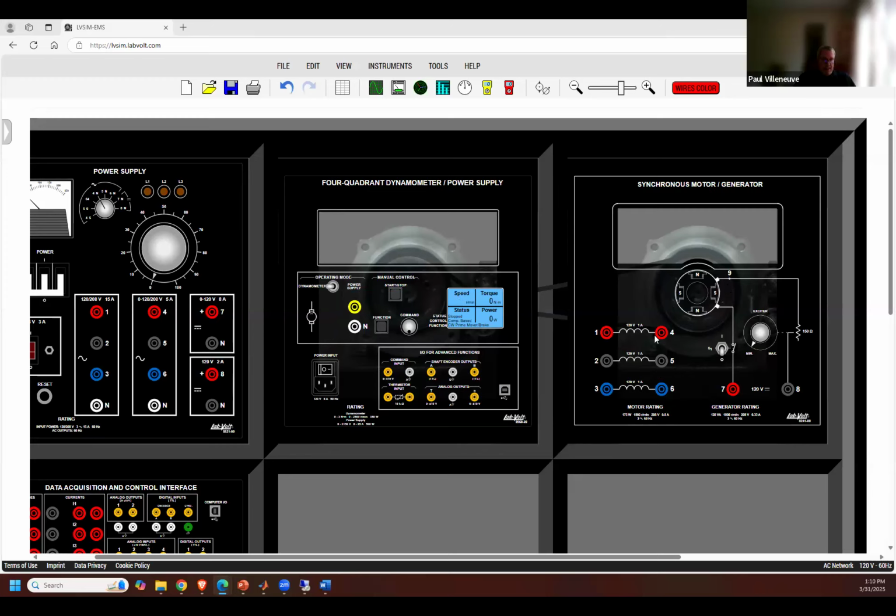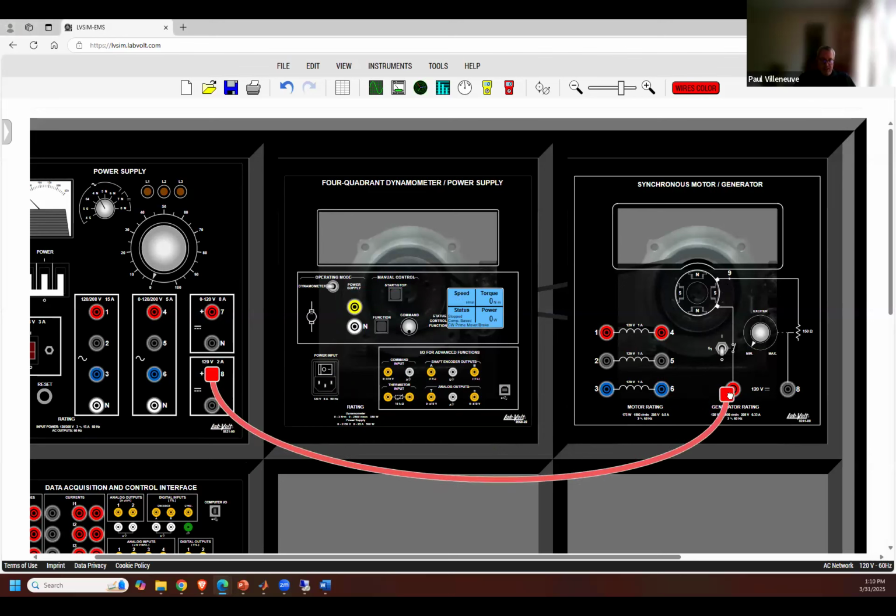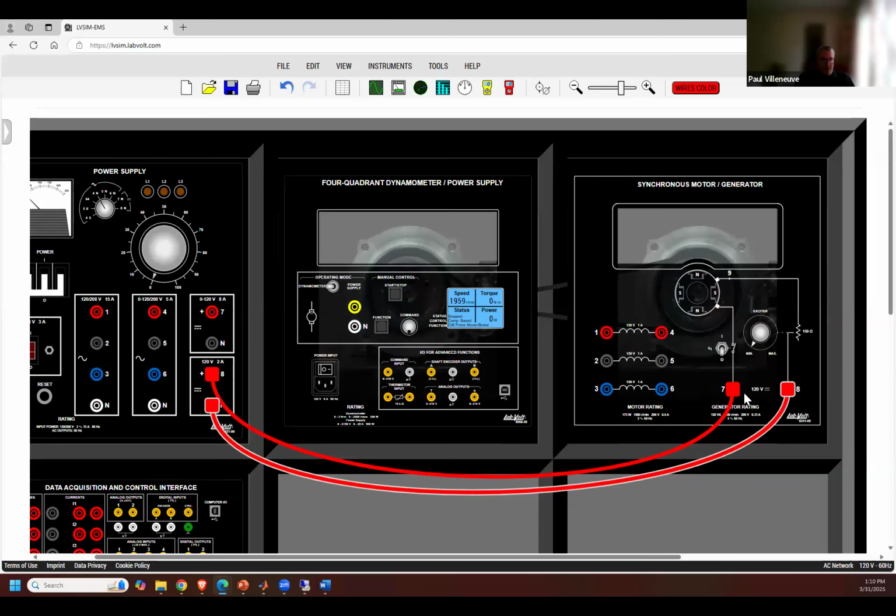So the way that I can get a magnetic field is I'm going to go ahead and run DC into the field winding as shown here. So this is just plus minus, and it's going to be 120 volt DC, not AC. So remember, it needs to be a constant magnitude and not alternating. So we need to run positive DC there. And you can actually follow along. This is an on-off switch just to indicate is the field on or off.